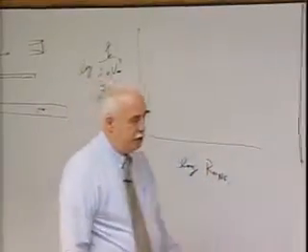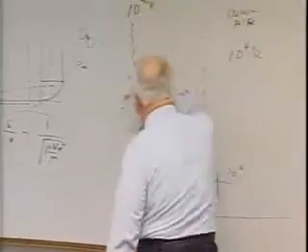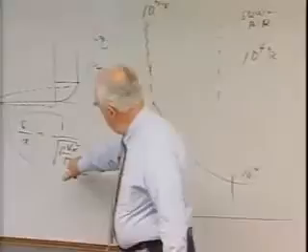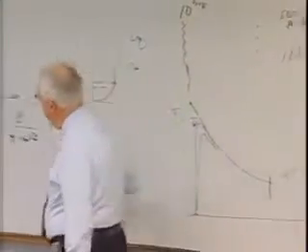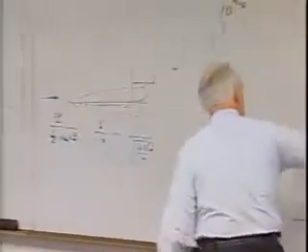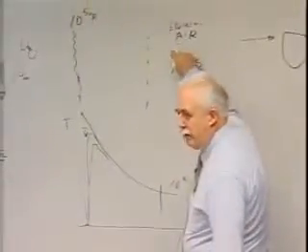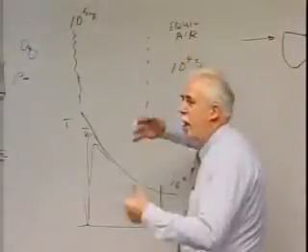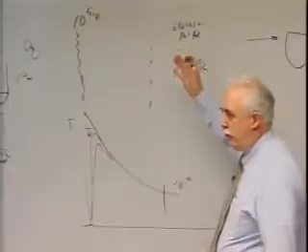All I do, as I go across the shock, the density, velocity, the mass flux is conserved, obviously. The viscosity is what changes. I'm going to use the normal shock, equilibrium air viscosity, because that's more characteristic of everything going on in what the Russians call the protective shock layer.